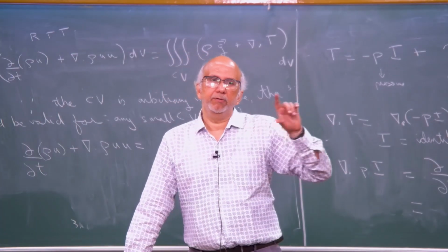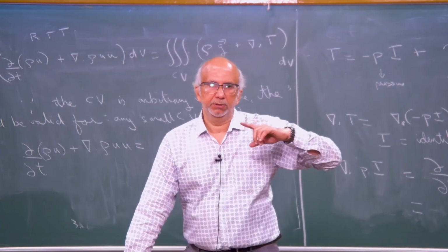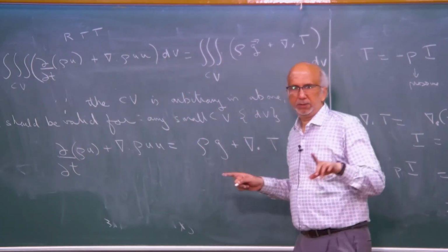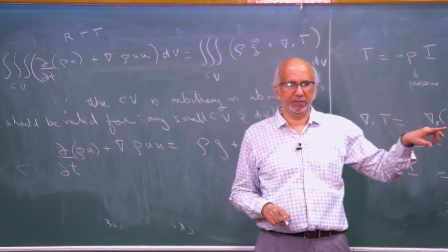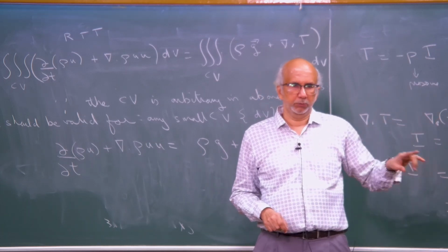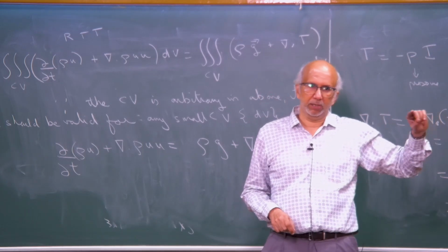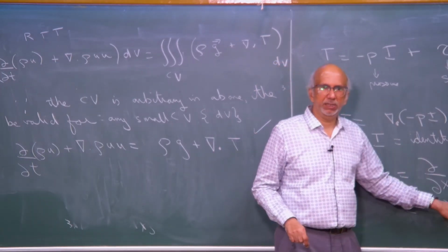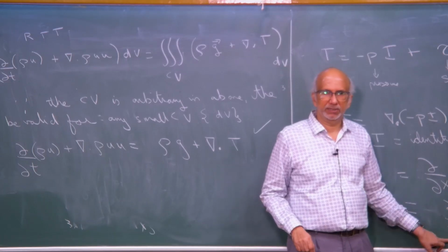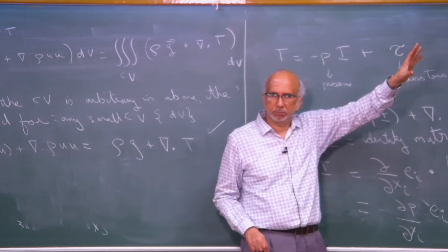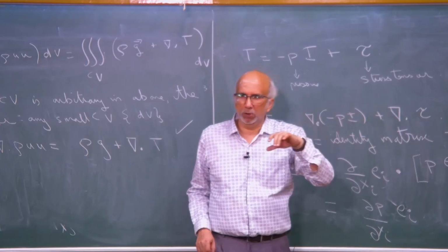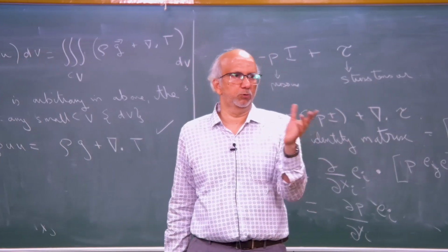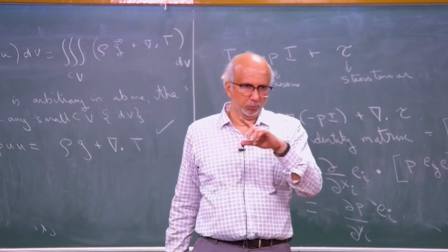So, when you write the Navier-Stokes equation, this is actually a vectorial equation, 3 components x, y and z, or 1, 2 and 3. So, when you write in the direction 1, when you write in the direction x, you will get minus dP by dx, that is the term which comes. So, you have to get comfortable with moving from vector notation to scalar equations by doing the components.